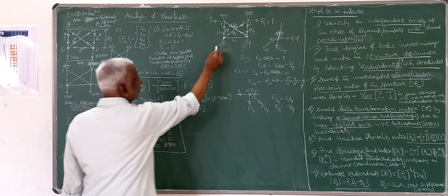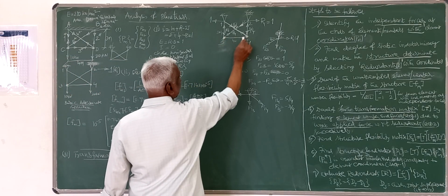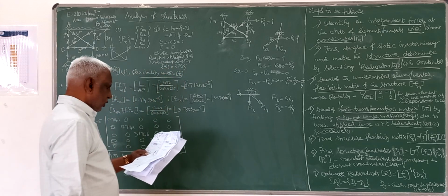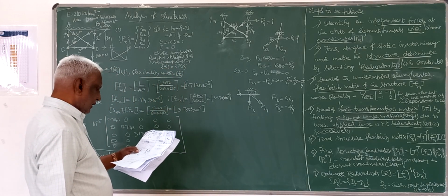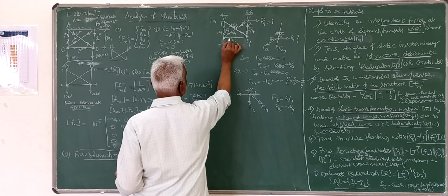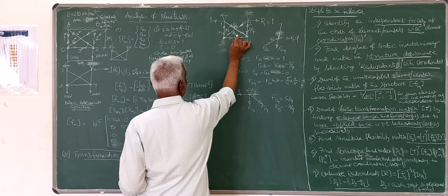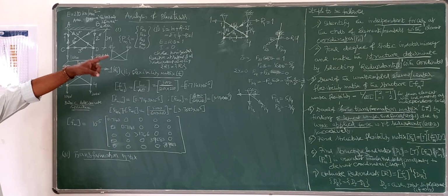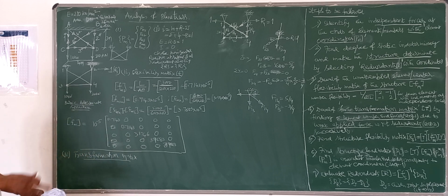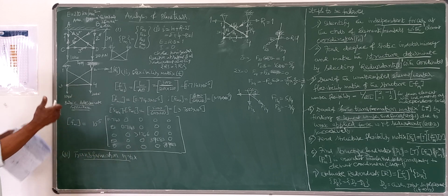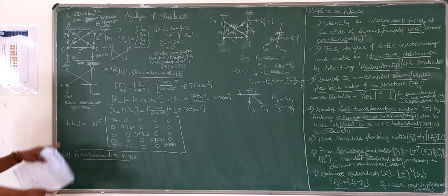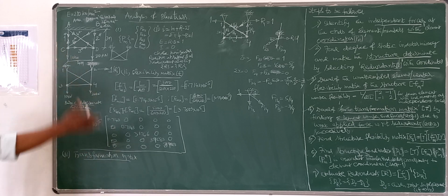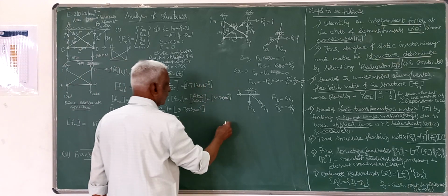So then you take either joint 3 or 4 and you can find out the force in that particular member, and that force will be the tensile force, and here I will get 1 as the force. So that much analysis you have to do for finding the transformation matrix. Whereas in a beam it was easy, we just took each beam independently and applied the equilibrium conditions. Now we have to do this method of joints, and that is why it is a lengthy process, the Truss analysis. You can do that straight away.